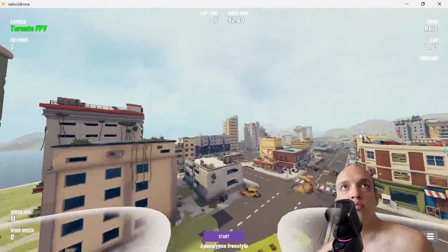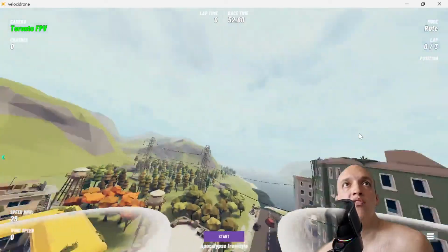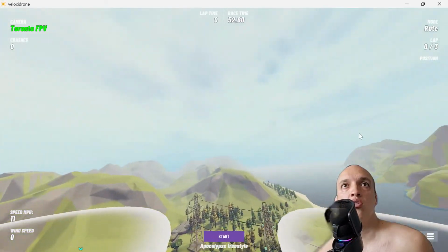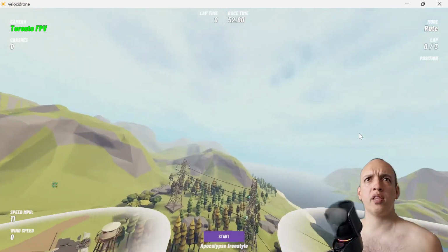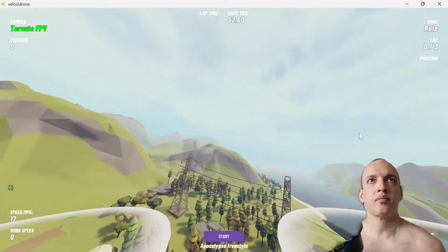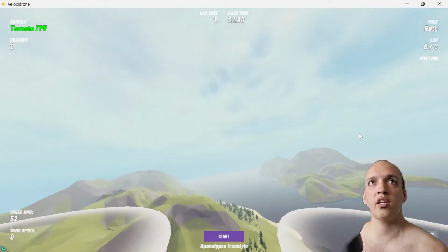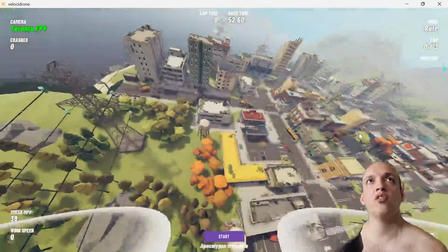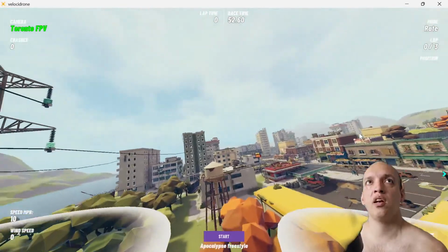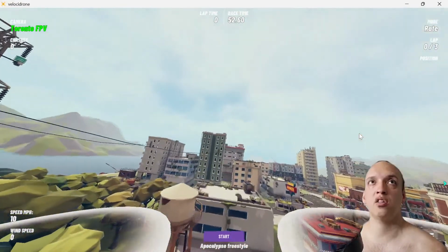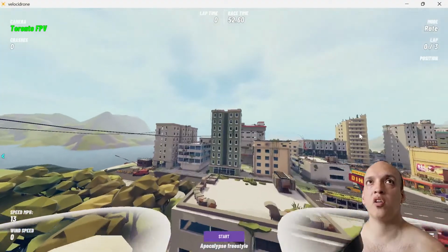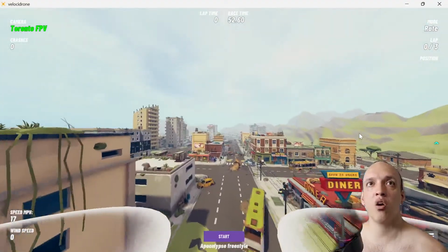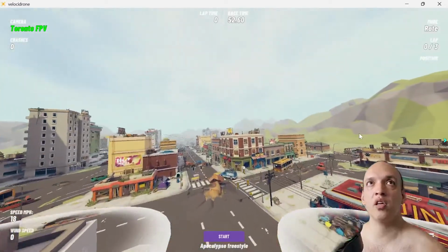So now the first thing that you should start doing is kind of go above everything. Just go up here and just learn throttle control, right? Throttle control is one of the most important things. If you are continuously throttling, you're just going to go up to the sky and it's never going to stop. So you need to figure out what level of throttle to keep you kind of hovering. And then you have to balance it. It's not something that you just keep in one spot. You have to learn to balance it because the quad will constantly kind of go up and down. So you got to balance your throttle. That's the first skill and most important thing you got to know.